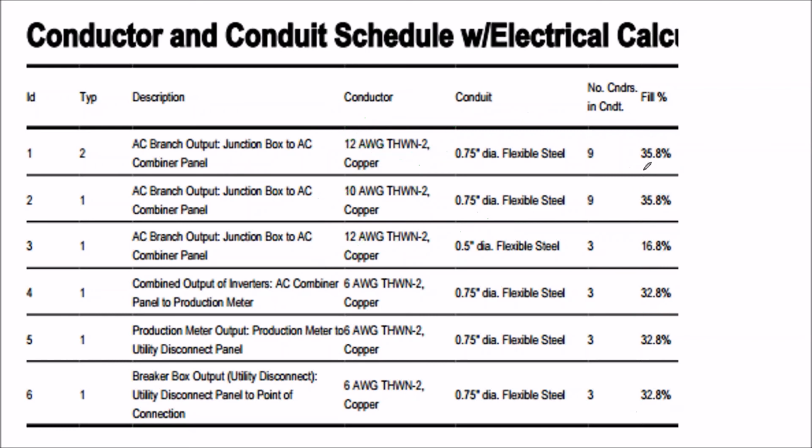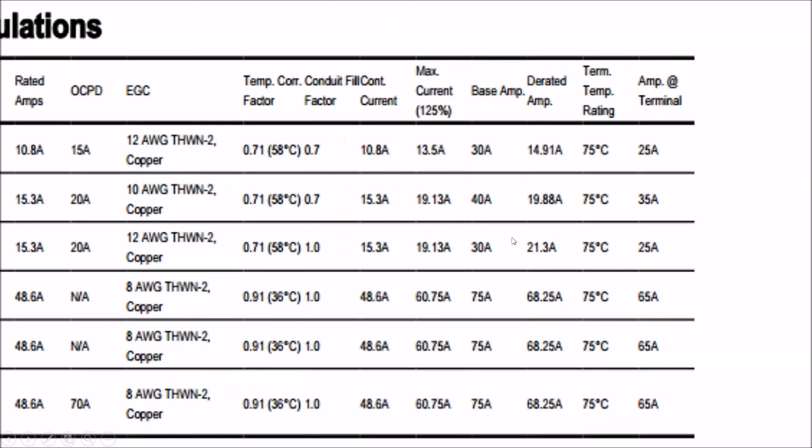But this is what I'm saying, it's a learning tool. It's also a work tool. An amateur will do this and then go out and buy a whole bunch of different wire sizes. A pro will take a step back and say, no, it's okay for me to upsize my wire. I'm going to keep my fittings and connectors and conduit sizes and wire sizes as uniform as I possibly can. It also shows an inspector that you've gone through and calculated your conductor fill for every single conduit run on the project, which gives them much more confidence in you if they've never heard of you before.